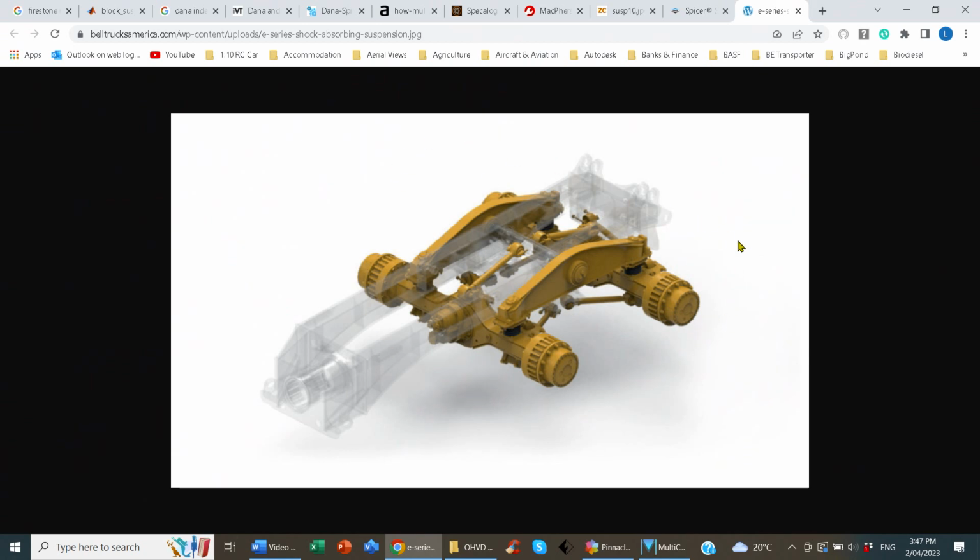This is a walking beam. On each side of a bogie, there's a pivoted beam. That pivot runs across the vehicle, the beams run along. And essentially, it allows each wheel to move up and down. Because there's a beam here, and it's a pivoted beam, if you hit a 100mm bump here, this point here will only go up 50mm. So it smooths the ride.